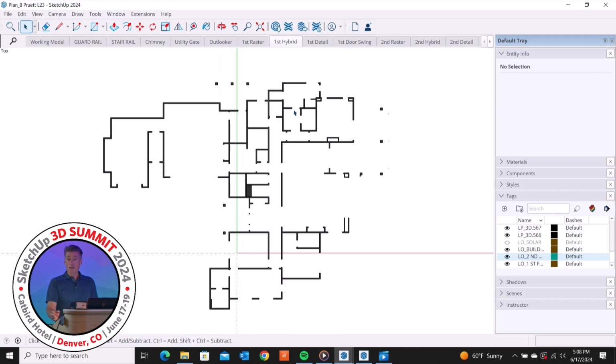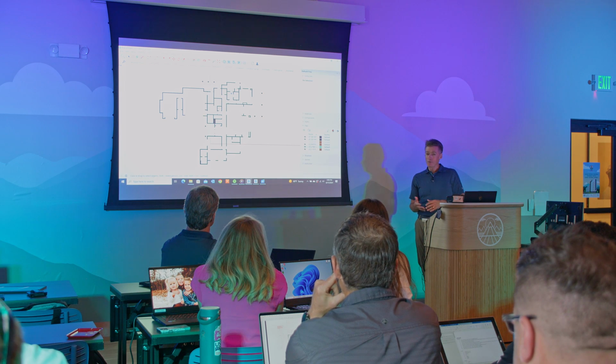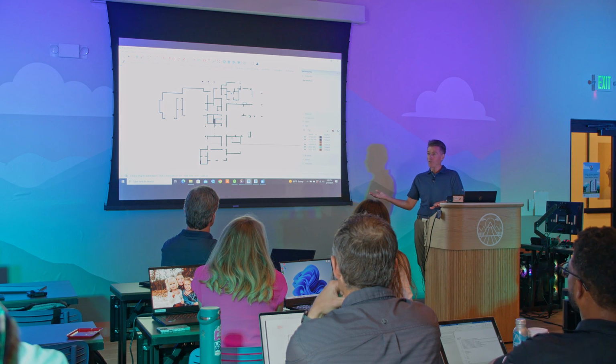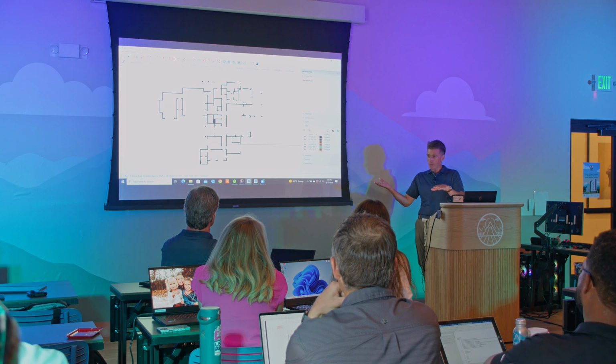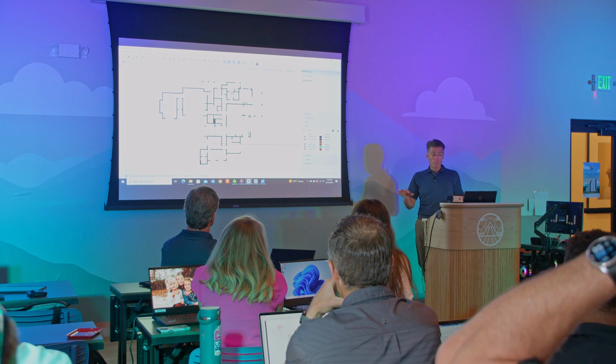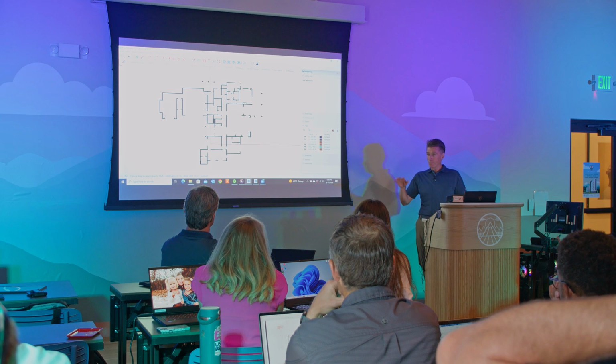But what's nice is it's an active section plane, so I can shift it anytime I want. And if, as I'm developing the drawings, I find that I've got this thing set at like 2 feet 11 because I'm cutting through all the countertops and I want to be just above that, but not into the uppers, I can adjust. Or if I want to make sure I capture as many windows as I possibly can, because I have windows with sills all over the place.